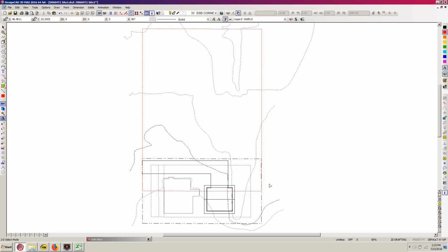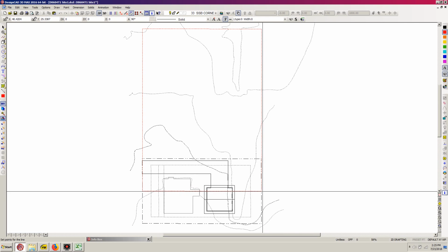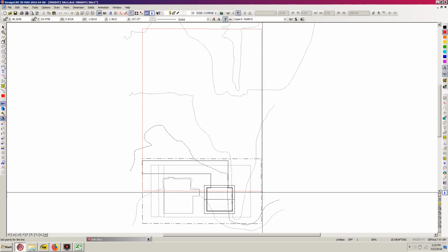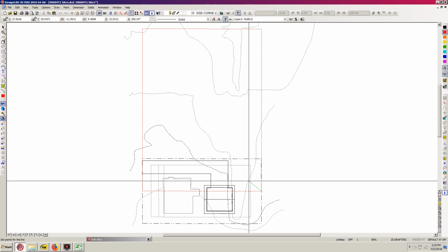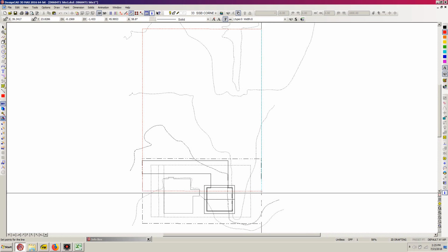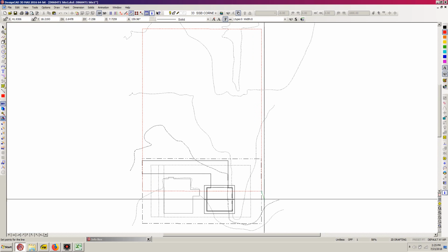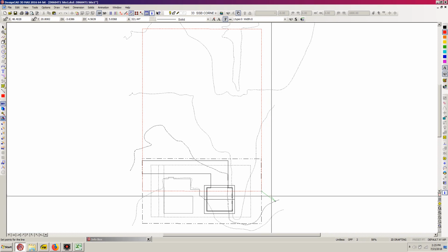So here, I'm just going to hit V for vector, and I'm just going to leave these red because they stand out, and just right-click to this southeastern portion of our slope calc area, and just kind of come over to this line here. So I want to try to be somewhat perpendicular to the previous slope line and the next slope line. So I'm just going to hit K here, and you can see I have 2 points set, and hit my scroll button to initiate the vector.